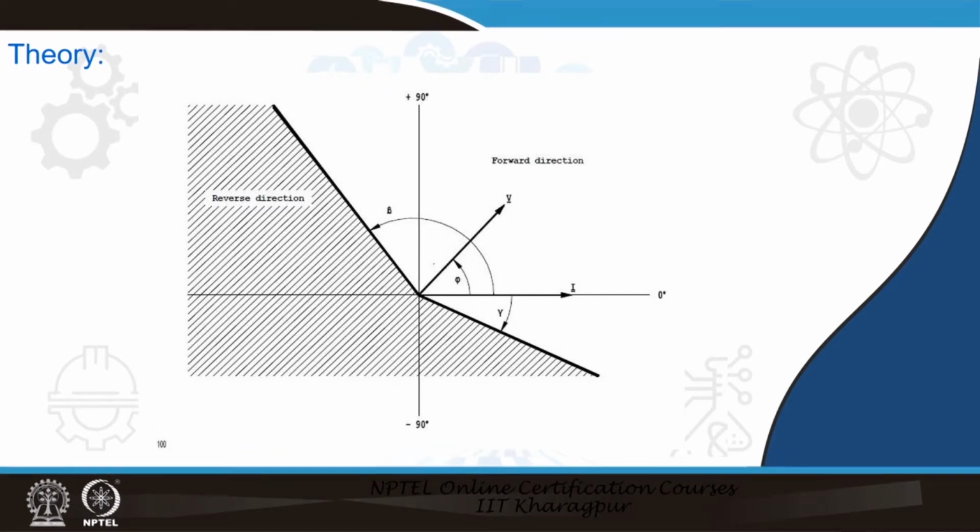So, therefore, this phi can be varied in a range with respect to the current. Now, for a specific case, the corresponding forward fault is where the current leads or lags, so it falls in a range, and the range is defined as shown here. With the current as the reference, gamma below this reference on the negative side is the negative angle, and on this side the beta angle is the leading angle. So, this is with respect to this current.